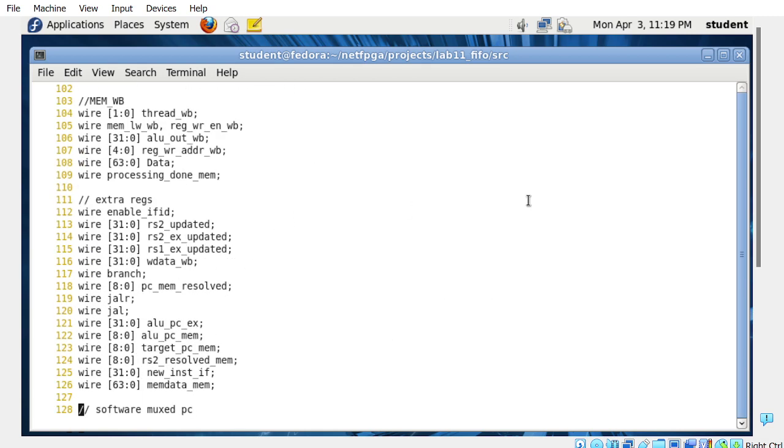And I'm taking out the header pointer as output from the FSM and giving it to the register file and storing it in the 31st register, which holds the address of the starting packet which we need to process.